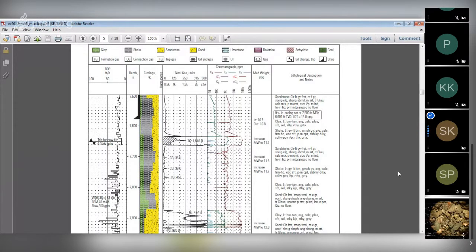There is a motor inside the unit which sucks the gas, and then it goes to the gas system, which calculates C1, C2, C3, C4, IC4. These are all the components we can see, measured in ppm.